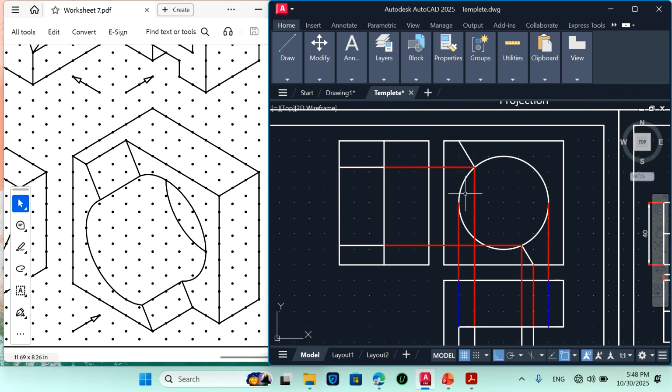So first we need to identify in the side view. When you see, these are the two boundaries of this curved surface. So draw the projection line from here to here, and again you draw the projections of this surface from here till this.